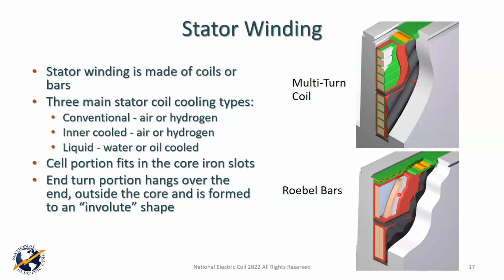When it moves away from the core, it discharges very high current coming from the core and damages the insulation quickly. In a non-cycled application, a lot of those machines can fail in as little as 5 years of operation. I may have some pictures I can show you of spark erosion later, but the important thing to know is that if you have good side ripple, a good mechanism to keep the coil tight in there, you should be able to avoid it.